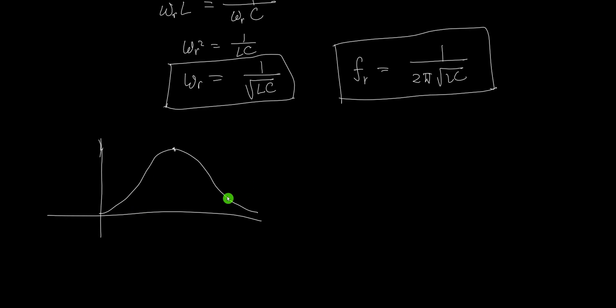So if it looks like this, then if you observe, if you can describe or differentiate the value at the maximum and at this part of the response, the difference between the currents is just very, very small. You cannot really exactly say that they are maximum if you are in this part. So therefore, it means the selectivity of your circuit is poor.